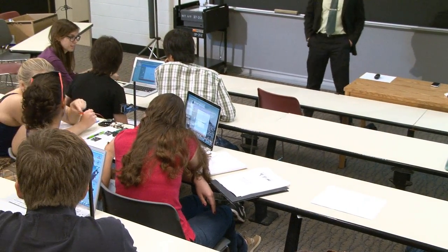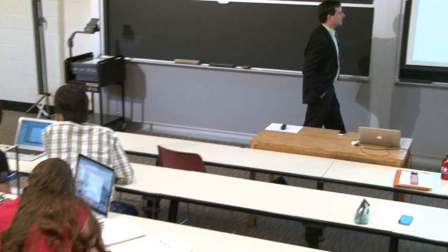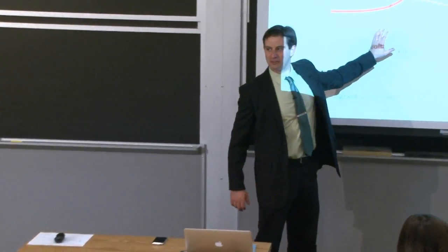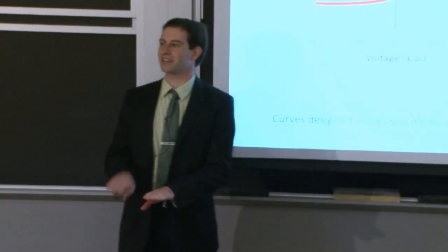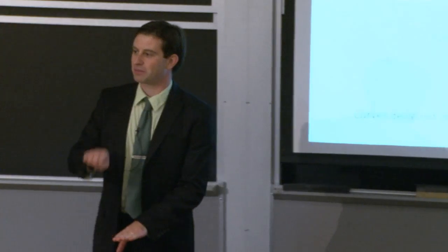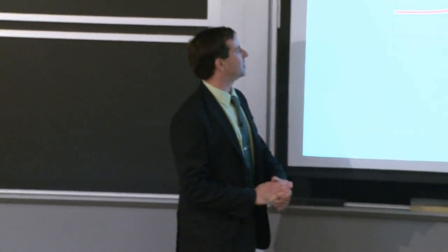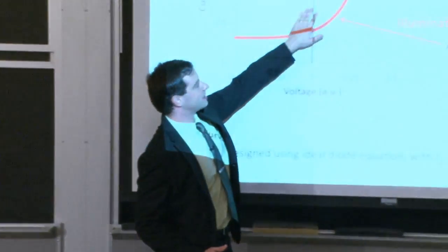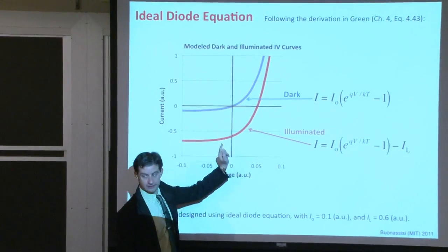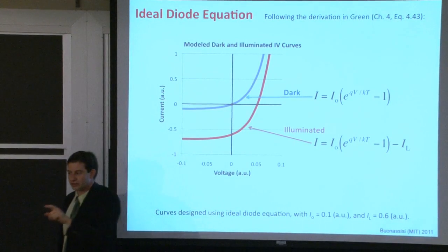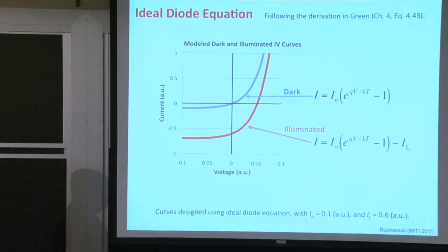So now that we have the basic IV curves rolling in, what I'd like you to do is modify the height or the intensity of the light. And the easiest way to modify the intensity of the light is to move the light position up and down. Right? So modify the intensity of the light and see how this IV curve changes. Note the y-axis scale, which might change as well. It might rescale depending on the condition.